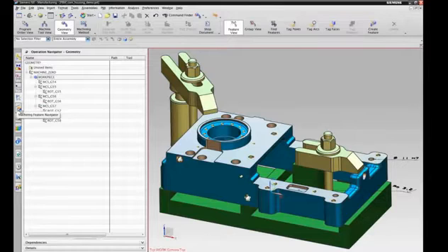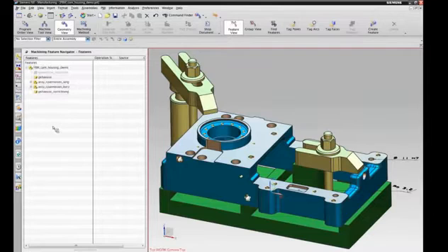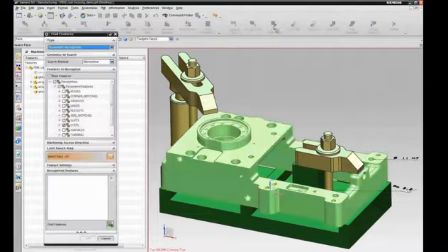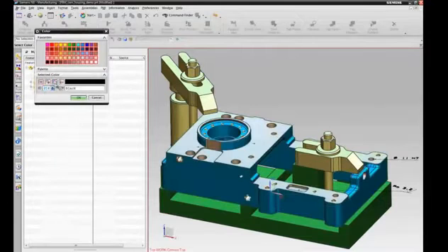I'm switching from the operation navigator to my machining feature navigator as a first step, and I'm now actually going to perform the two feature-based steps to get an automatic programming for this part. I'm starting with my find features command. I have that pre-configured to use parametric recognition. I'm looking at my entire workpiece, and this is a list of feature types that come with NX CAM out of the box, and I've selected a few of them. And normally I would just run across the entire part, but in this case I'm going to not run my recognition on the entire part.